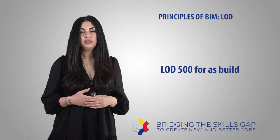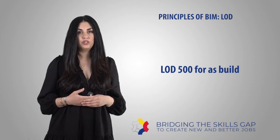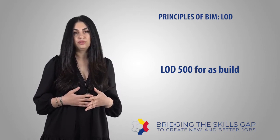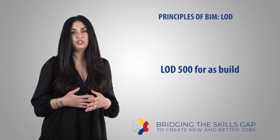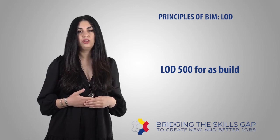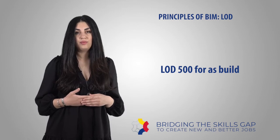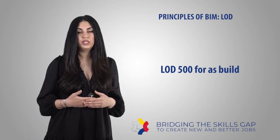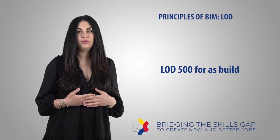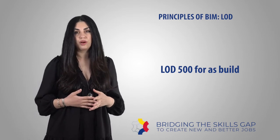So, earlier I said that level of development can be related to project phases, but remember that officially they are not. It just helps to picture the milestone. There is actually no such thing as an LOD 300 model. It doesn't make sense to require the same LODs for all objects in the model. I know it might seem easier, but you will lose too much time detailing objects we don't really care about.